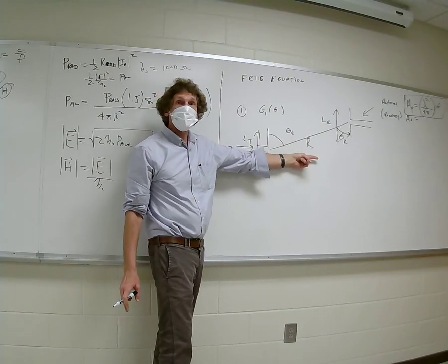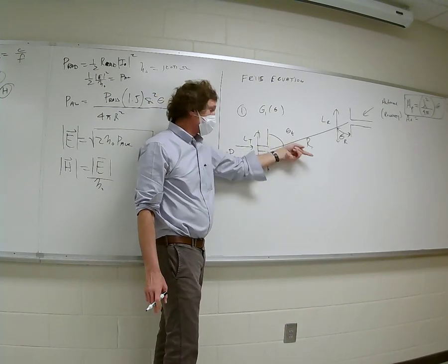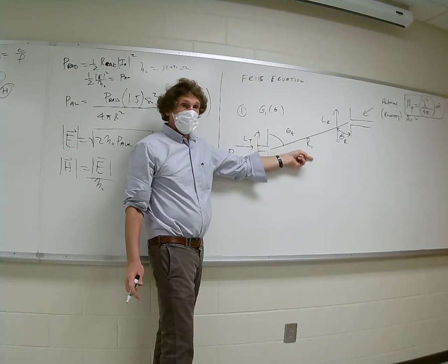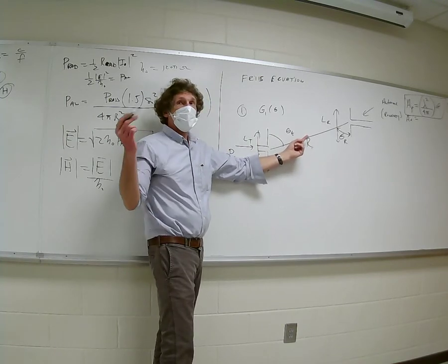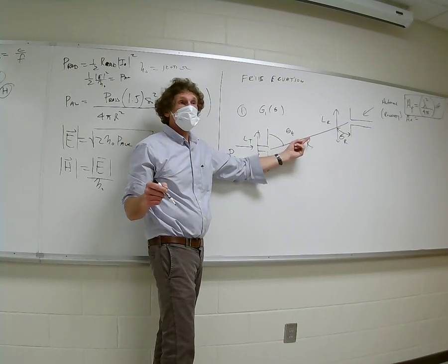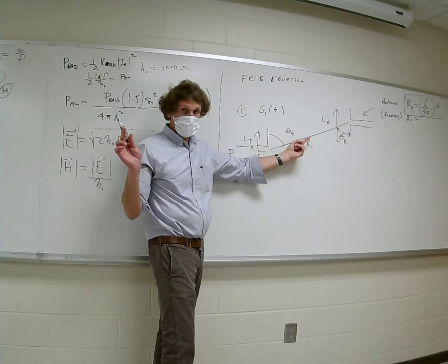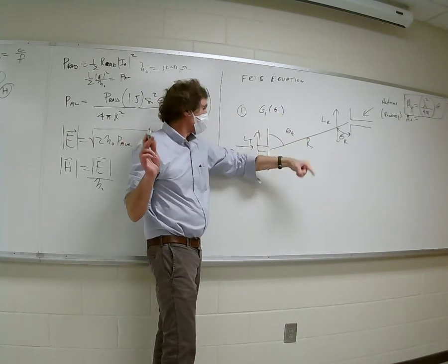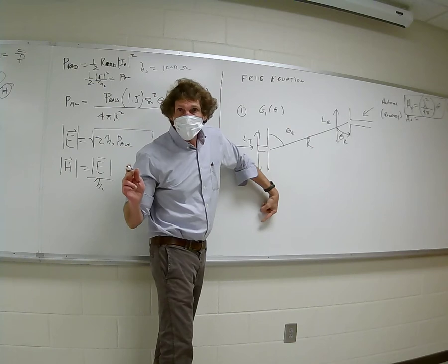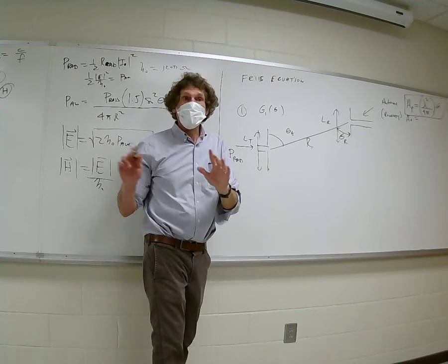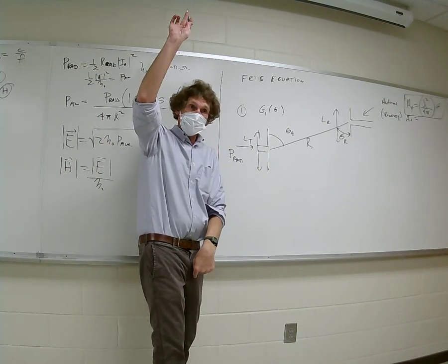Now listen to me carefully. When this angle is 90, it's 1.5. But if it's at any other angle, you have to take 1.5 times the sine squared of that angle. Does everybody hear me on that? And what's the gain, straight up or straight down? 0. Remember, no power is launched off the ends of that antenna.